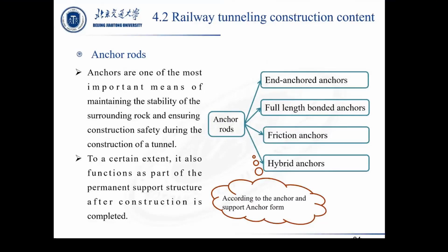According to the actual form of the anchor rod and the support body, it can be divided into end anchor rod, full length bond anchor rod, friction anchor rod, and hybrid anchor rod.